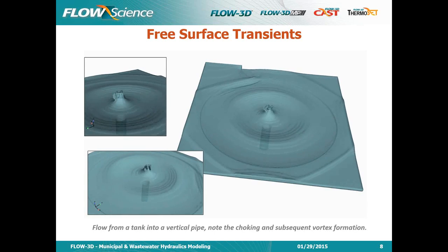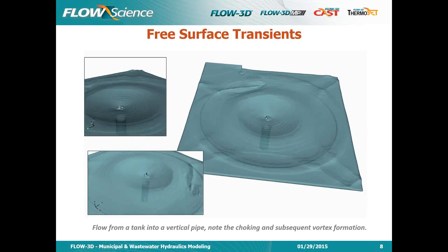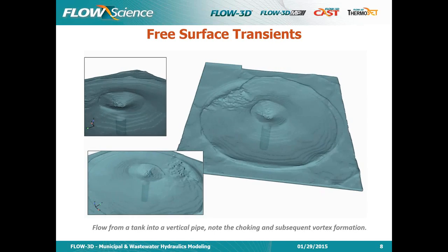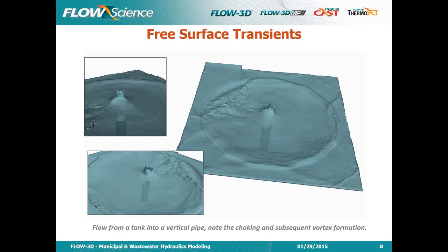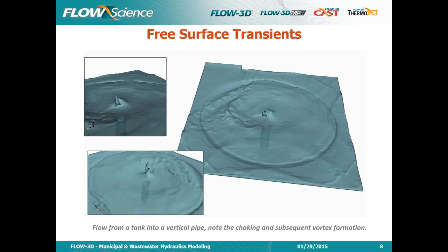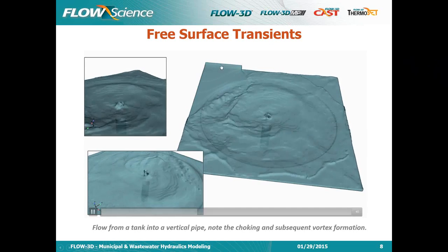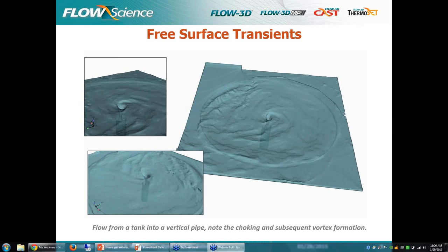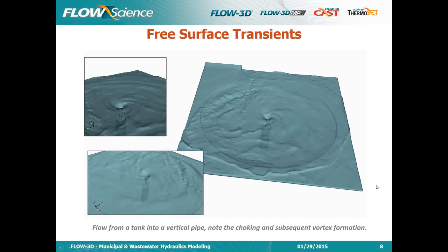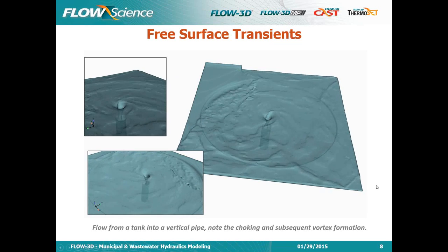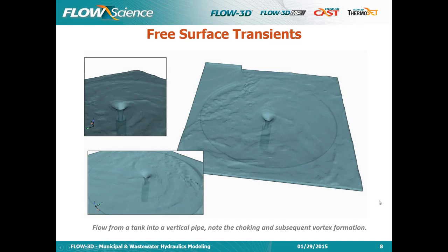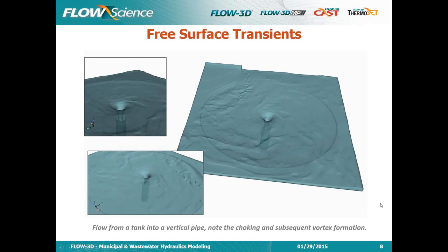So what you will see here is the formation of an aerated vortex core following the kind of initial choking transients we are familiar with. The flow is coming in the tank from the top left corner, and which is why the drainage eventually settles into a vortex type core.